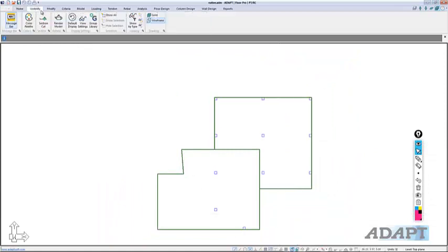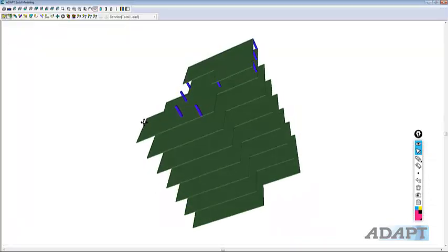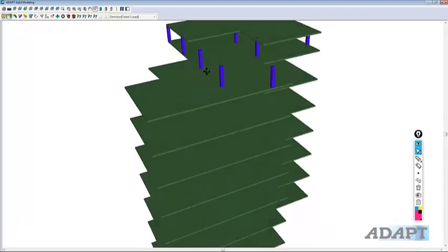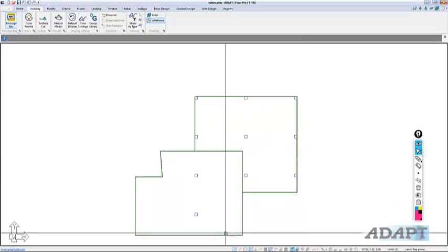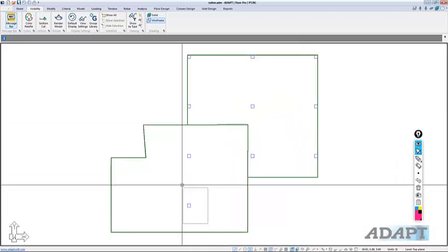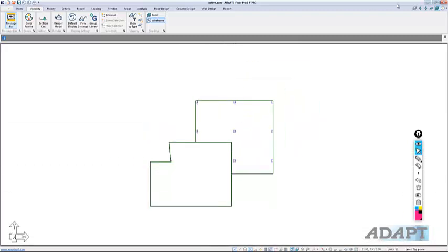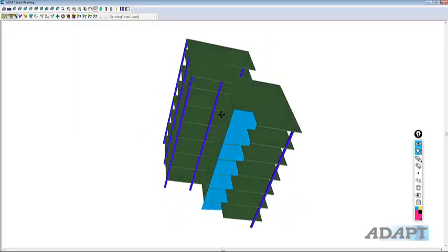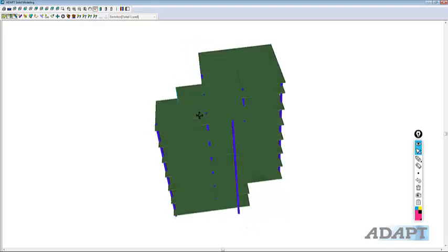Now what I have, if we go to Visibility under the Render Model tool, you can see I have something that looks like this. And I have 3 columns here I actually want to delete out of there also. Okay, so let's delete those. I'm still working in multi-level mode. If I go back to default display, it's going to show everything. And we'll go back to the render model. Now we have something that looks like so.